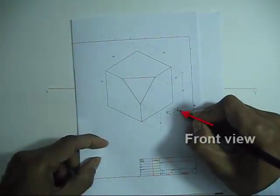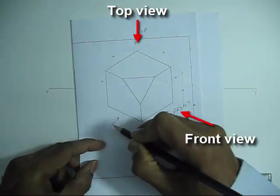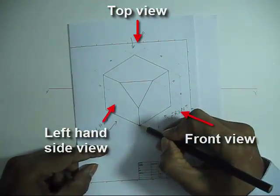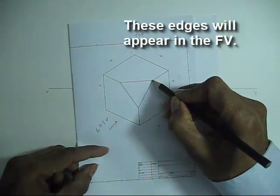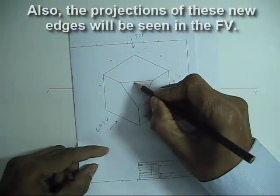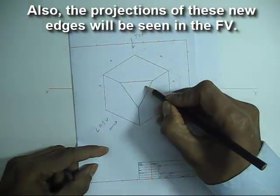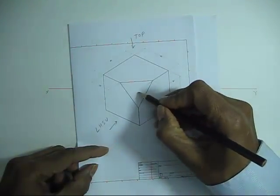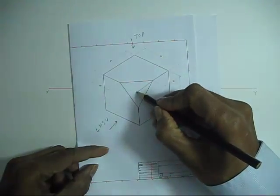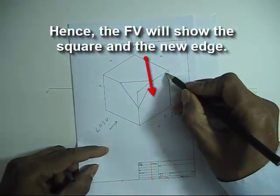So we will take this as the front view. This will be the top view, and this will be the left hand side view. The front view will show these edges. The new edge has been created, and the front view will also show the projections of these new edges which are inclined on the front view. So the projections will be seen in the front view, and these projections will make basically a square with a new edge.